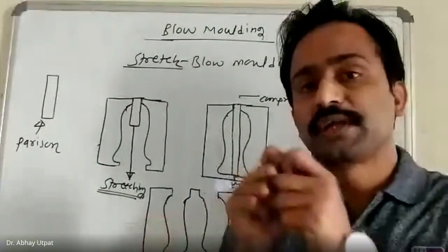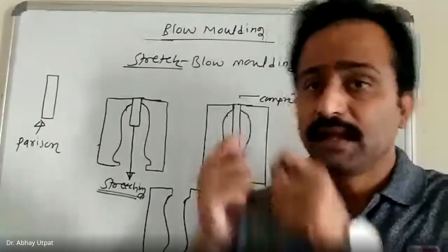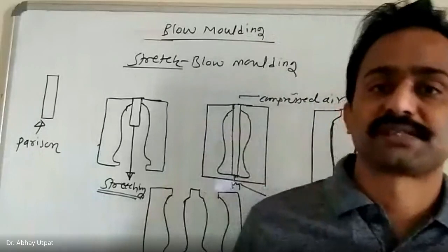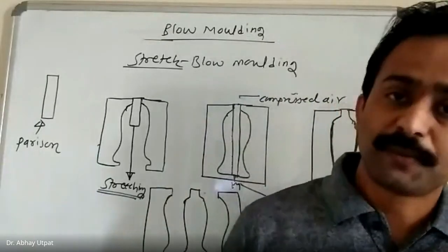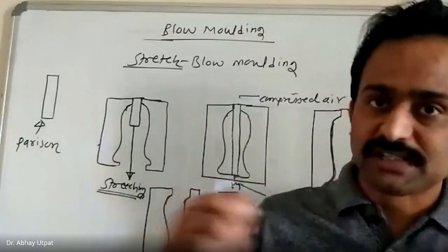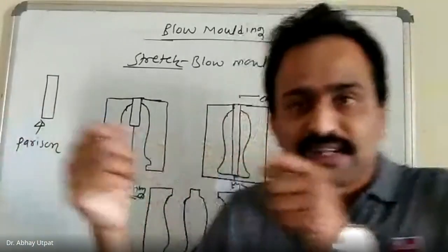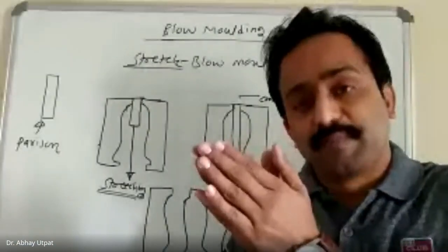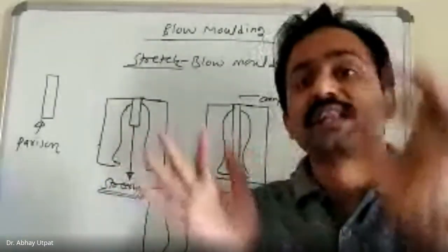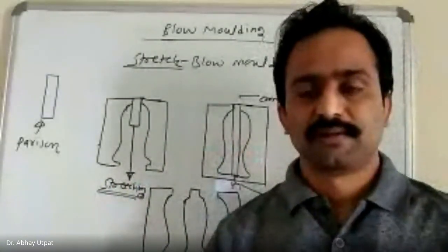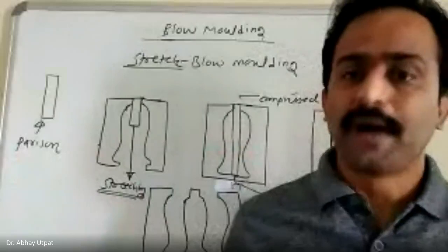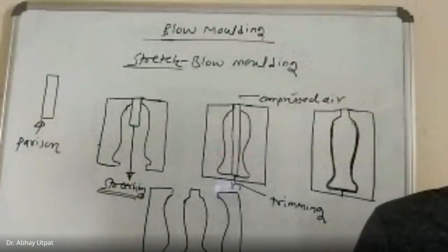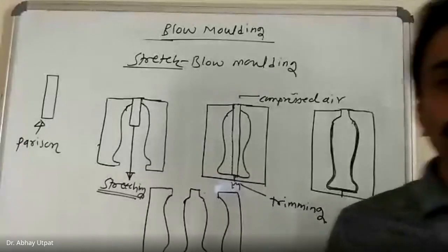Try to swell it without stretching and swell by stretching. Note the difference. When you stretch, the wall thickness decreases a little and swelling is possible with less effort. So the parisons are sometimes difficult to swell, difficult to blow only.